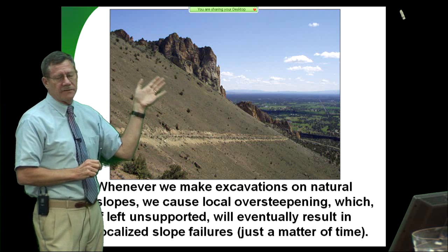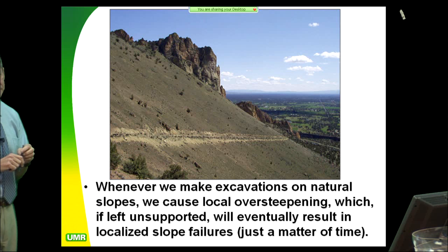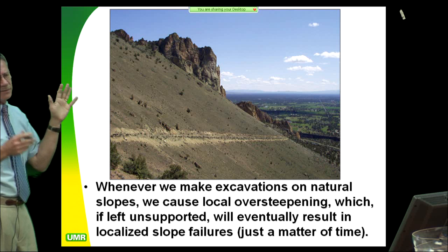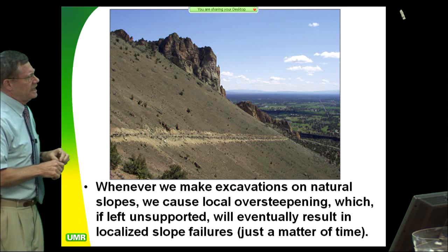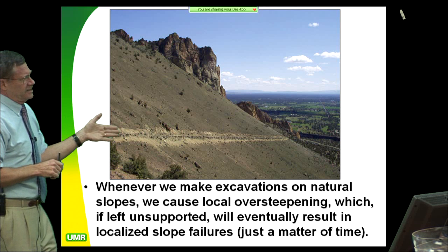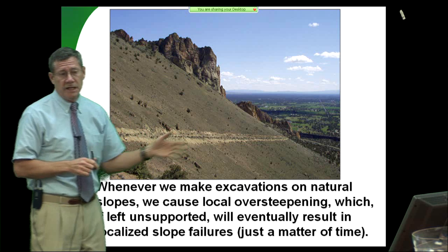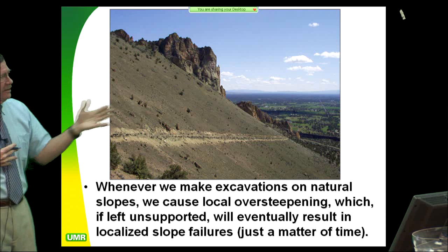Its factor of safety is 1.01, 1.03, given the environmental extrema to which it's been subjected. That's what the factor of safety is going to be when it's raining a lot for a while. So if you put a road in here, it's just a matter of time before you're going to lose this slope. So all my biggest Department of Transportation problems out west, there they are.